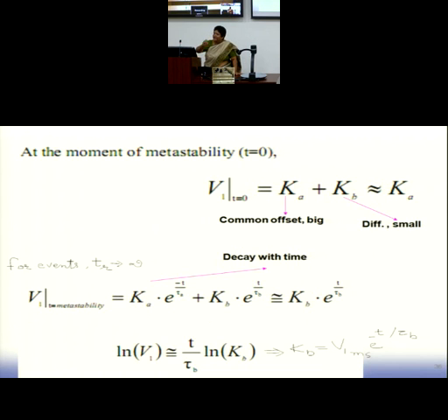The more I wait, the more chance that the system will stabilize. The more waiting time I give to this D-latch, the more chance that the system will stabilize and there would be no failure happening. That means if I try to find out the probability of failure, it is inversely proportional to this exponential rise.